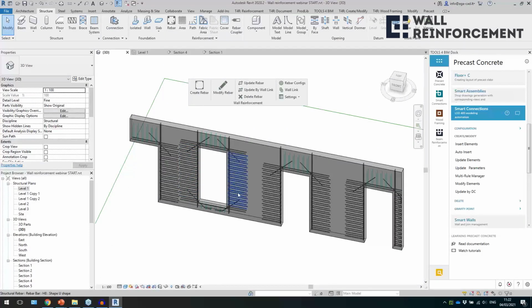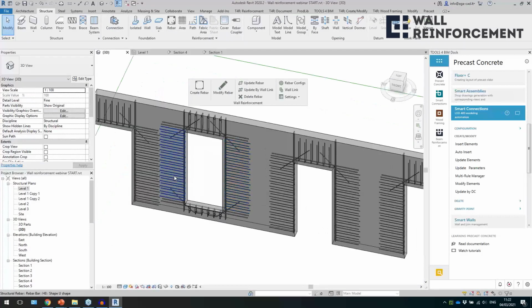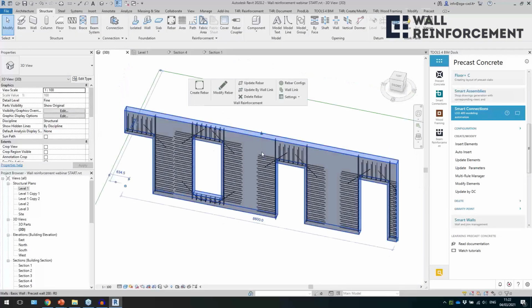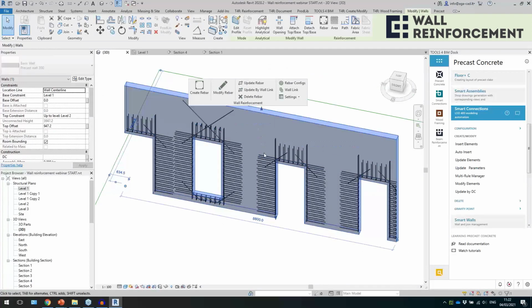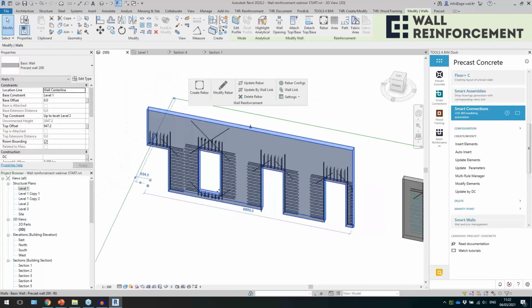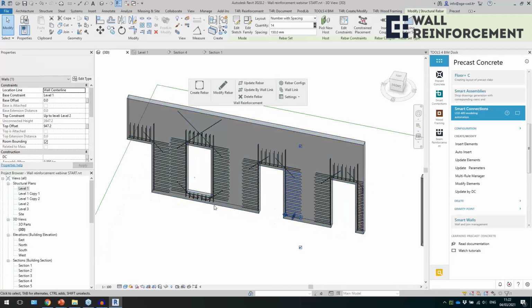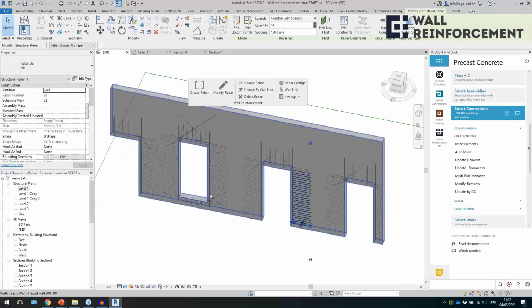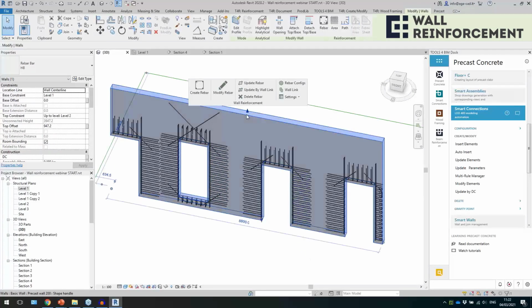So you see I have, again, very similar to the previous, U-bars, O-bars, straight bars around the opening, and then diagonal bars, right? But what's the difference here is that you can create that only for doors, because previously it was placing U-bars at all the perimeter. Now you can have more control for that. So I'll change that and I will show you a few new options for that.